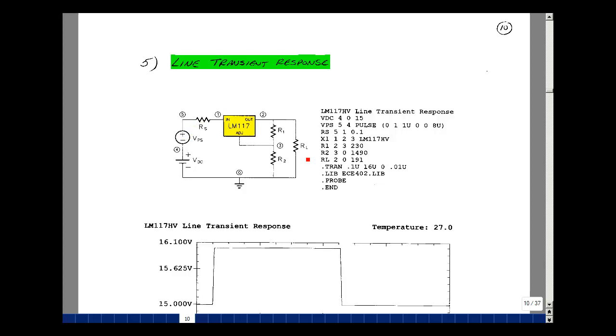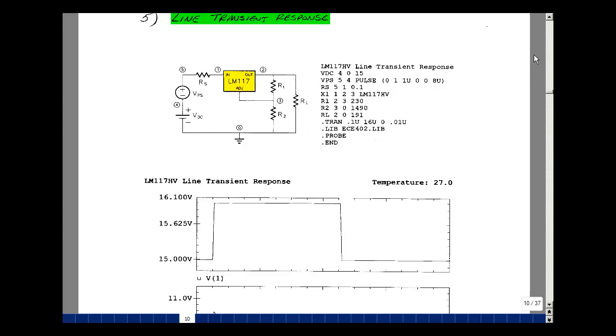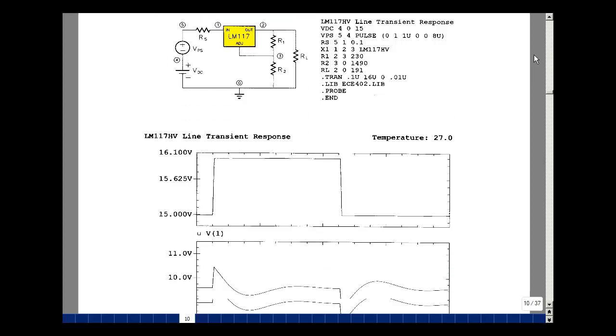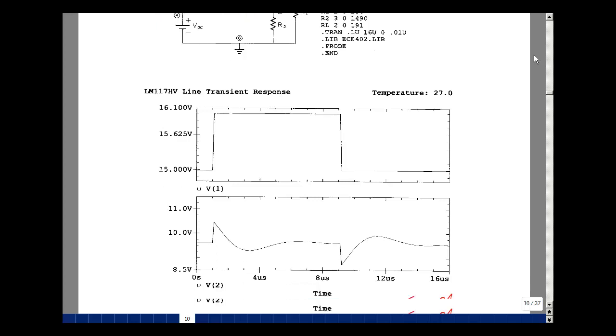So here's actually a 1 volt spike, mimicking the test that's in the data sheet, and watching what happens at the output of the regulator. Prior to this happening, we're getting about 9.5 volts out, and then we get this jump in voltage. It comes back down again, and then there's a corresponding jump and kind of an undershoot and ringing, and eventually comes back to the 9.5 volts again. And then on the back side it does the same thing.